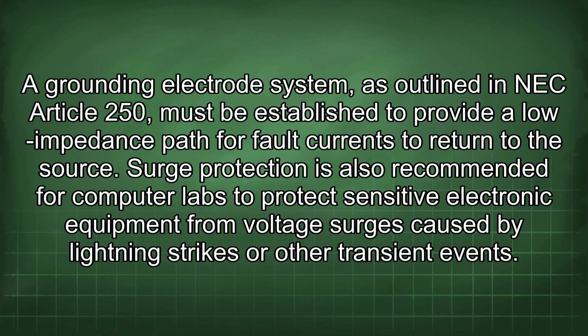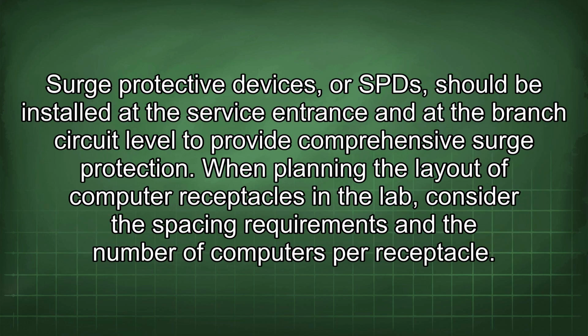Surge protection is also recommended for computer labs to protect sensitive electronic equipment from voltage surges caused by lightning strikes or other transient events. Surge protective devices, or SPDs, should be installed at the service entrance and at the branch circuit level to provide comprehensive surge protection.